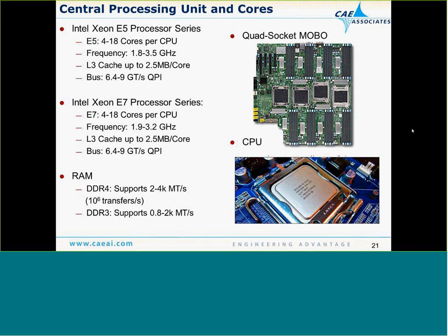Another question I get on tech support quite a bit is: if you have 2 8-core processors on a motherboard at a frequency of 3 gigahertz running an ANSYS job, and let's say it takes 10 minutes, just to throw it out there. And the particular user upgrades their computer to one 16-core processor, and they run the same job, and they find out it takes 12 minutes to run. And a lot of times the frequency is even a little faster. So let's say it's a 3.2 gigahertz processor, 16 cores on one chip, and you find out it takes a little longer to run. At the end of the day, it's not just about the frequency of the CPU.